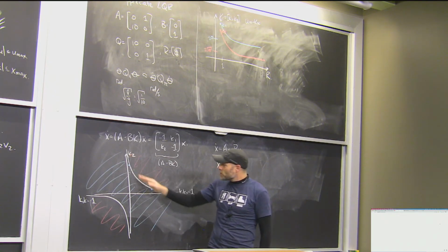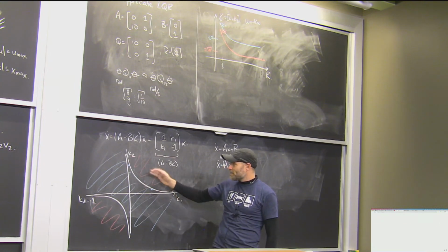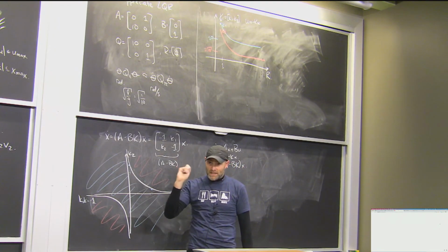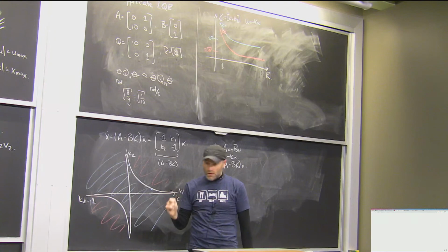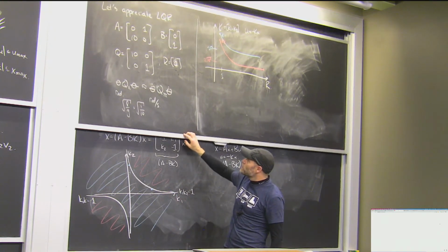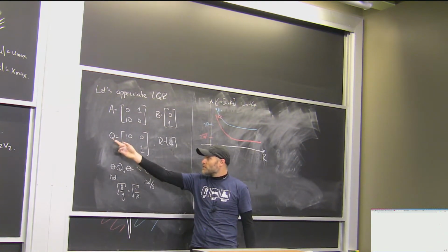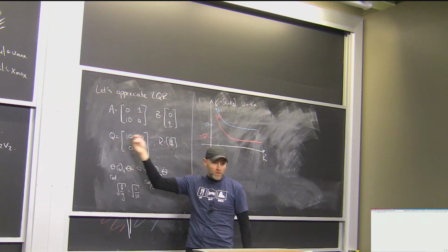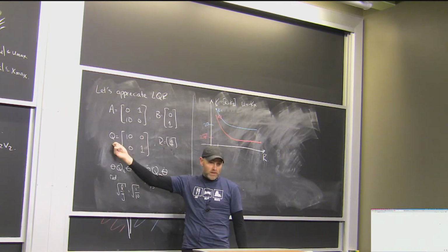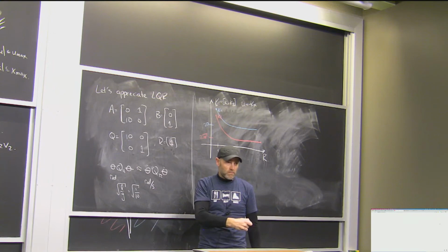But you should think about LQR as a better way. If I'm, as a human, just picking K1s and K2s, I can get myself into trouble. Certainly with an Acrobot, finding K1s and K2s that make this thing stable is not an easy task. And what you should think about as LQR is a different parameterization, where instead of mucking around with K1 and K2, I'm going to muck around with Q and with R. Every time I put a Q and R in, I get a stable K out, right?